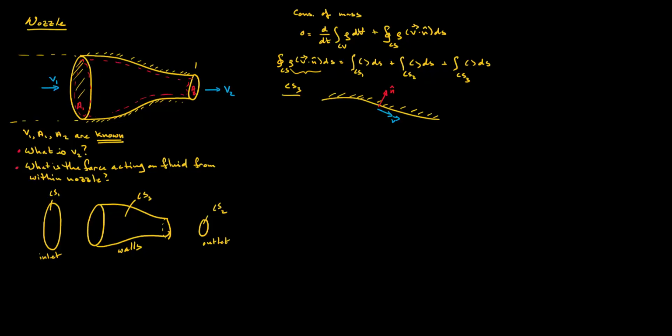It's also, walls are what we call impermeable, okay, which means that there is no flow going through it. So there's really two things here telling us that nothing much is happening at this control surface in terms of how the conservation of mass will be dealt with. Okay, so a wall is known as an impermeable boundary condition. There's no flow that can pass through it. So therefore, intuitively, you can already state that the wall will have no effect on the mass balance, which goes into the conservation of mass.